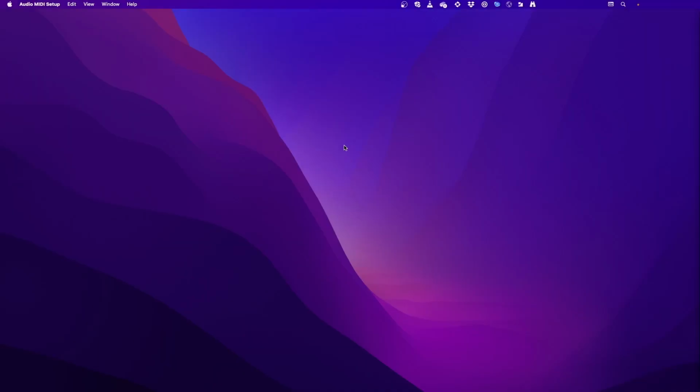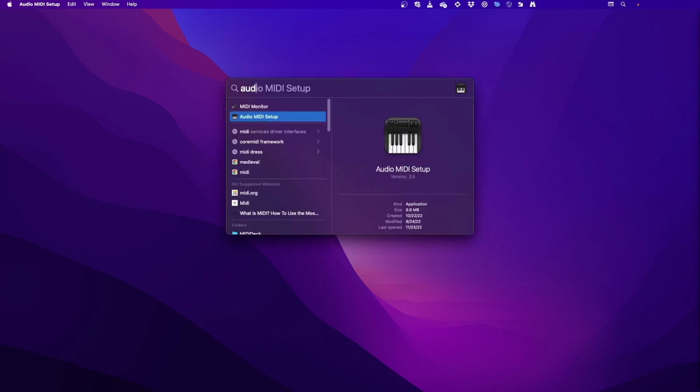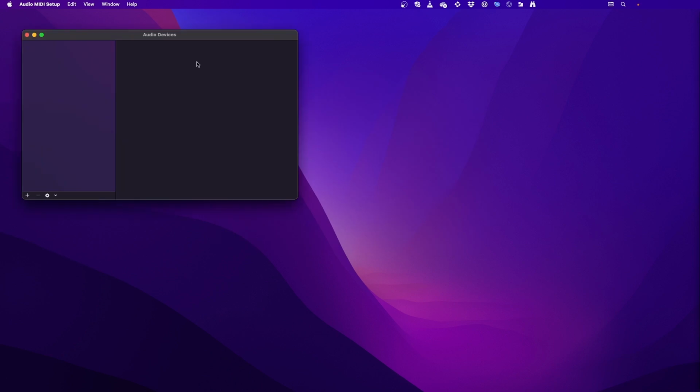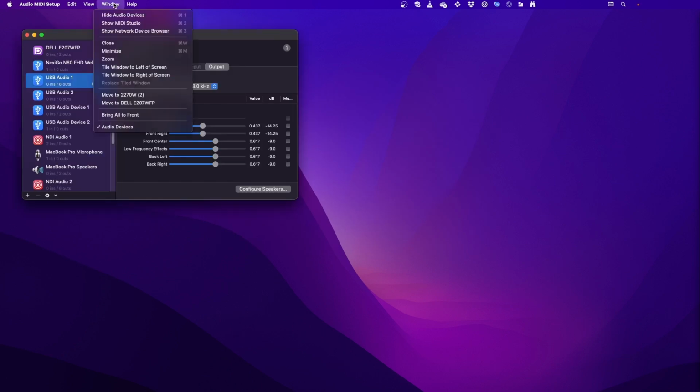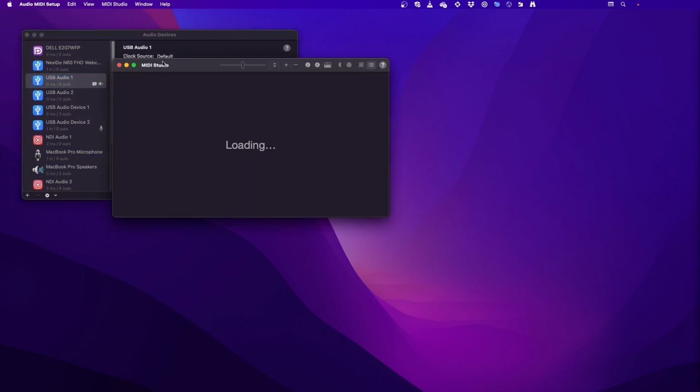I'm going to walk through how to troubleshoot after you get the code uploaded to the Arduino. And I am on a Mac here, so this is all going to be done from that perspective. I'll try and throw in what I know about Windows, but I hate to say you're kind of on your own there. So on the Mac, I'm going to pull up the Audio MIDI Setup option first and go to the MIDI Studio.